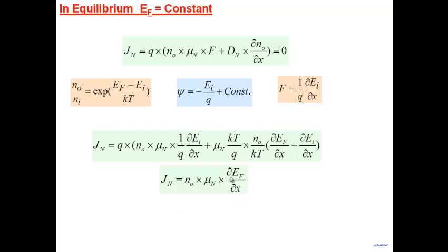Now this term by itself is important because note that in a semiconductor, what are the two driving forces for current? One is the field and the other one is the concentration gradient, right? This term encompasses both of them. What does it tell us? What is the driving force for current inside a semiconductor? A gradient in Fermi energy. That's what drives it. When you write it like this, it includes within it both the drift term as well as the diffusion term. That is the gradient in Fermi energy, which will drive the direction of current.